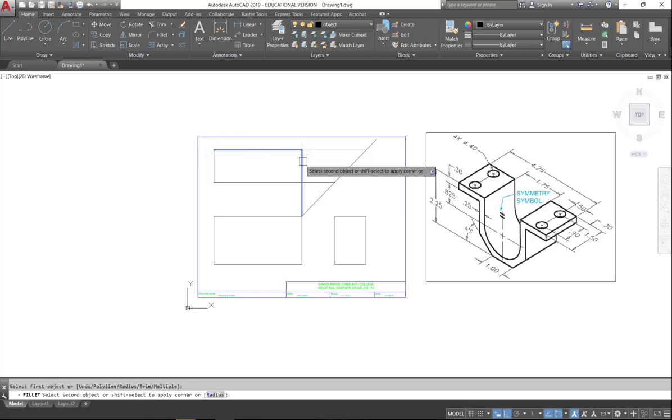So using my miter line, I was able to create my top, front, and right side view. This is the biggest that it's going to be. I know that everything has to fit inside the boxes, those 3 boxes that I just drew. So I'm going to again go back to my front view, and I can see that the thickness here is 0.3. So I'm going to offset 0.3. So I know there's my width. I can see that my distance here on the top side is 1.75.